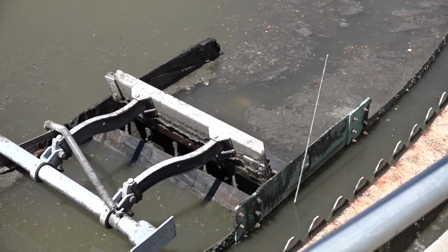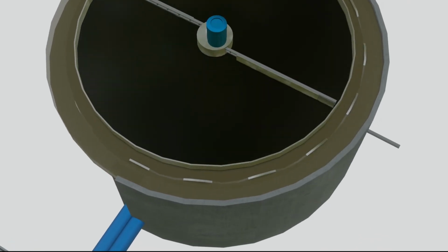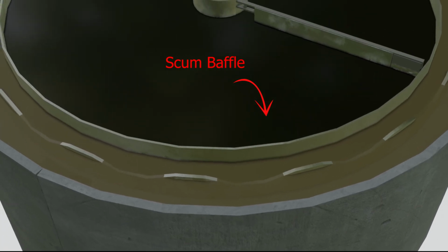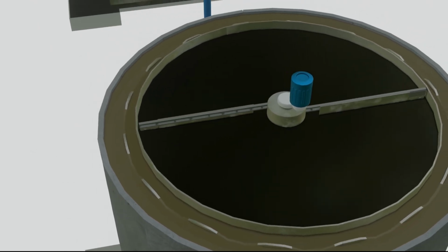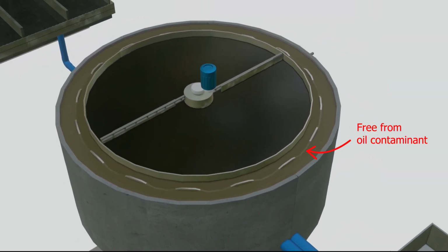The cleaner wastewater passes to the effluent launder that is located on the outside of the surface of the tank. This component is called the scum baffle. It is used to separate the wastewater from the scum and cleaner wastewater, so that the water flowing out to the effluent launder has no solid and oil contaminants.